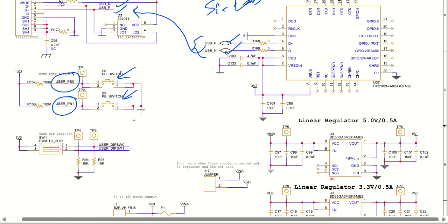There are scenarios where you need to set the IO pin as high or low all the time. It is kind of like configuring an IO pin as an input with a high or low input. For that purpose, you slide this one to the left side, it will become low, and you slide this one to the right side, it will become high.